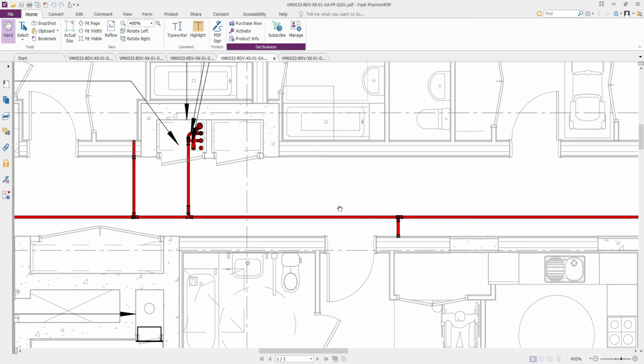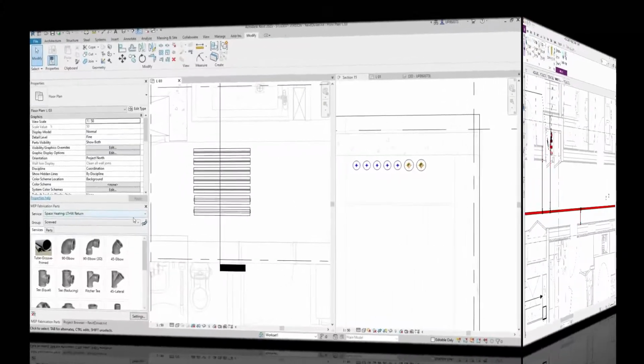No need for insulation. I will keep 165 millimeters distance between the wall and sprinkler to allow some space for the LTHW IV valves. And I'm gonna keep it at 2555 millimeters height from FFL to keep it between the domestic and LTHW pipes and containment. So there are no ups and downs, so we don't need any air vents and drain cocks. It's time to model it.